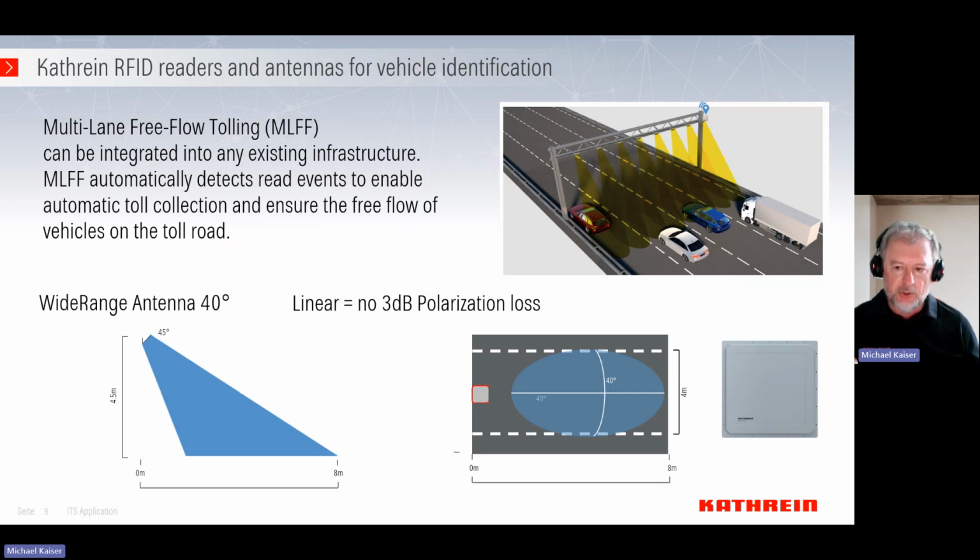This means with a circular antenna, we need to split the power into 2 planes. And this splitting into two planes to make the antenna circular needs a 3 dB splitter. This 3 dB splitter also has to cover the small signal from the transponder backwards to the reader.